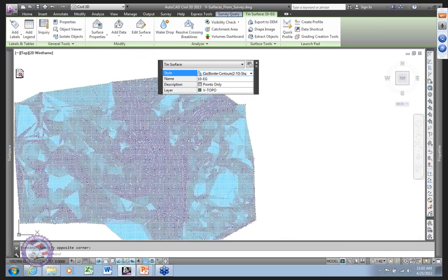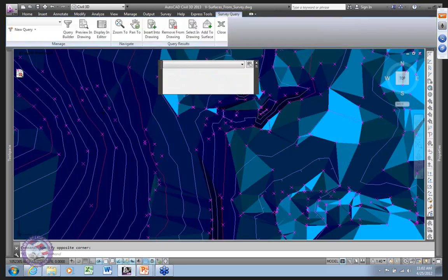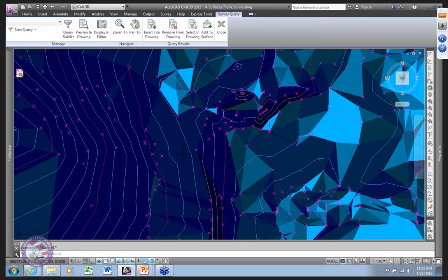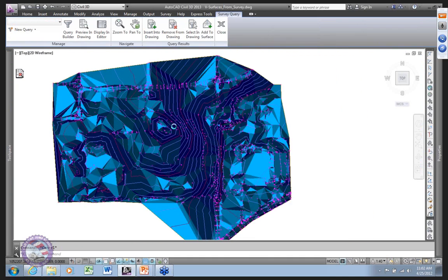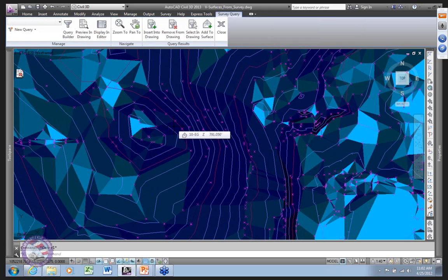I tweak my ranges. I'm gonna unselect here. Tweak my ranges, but now I got the contours coupled with that slope analysis. And what is this telling me? Okay, the closer the contours get together, the darker the color should be. Is that validated everywhere? And okay, so we get some flat areas, and you can see that real quickly.